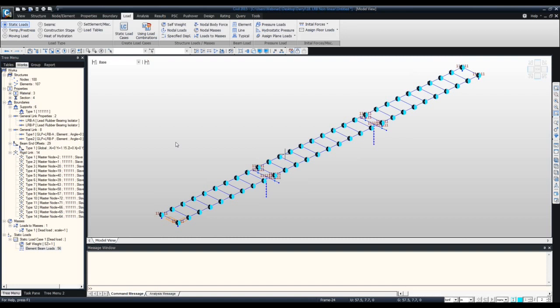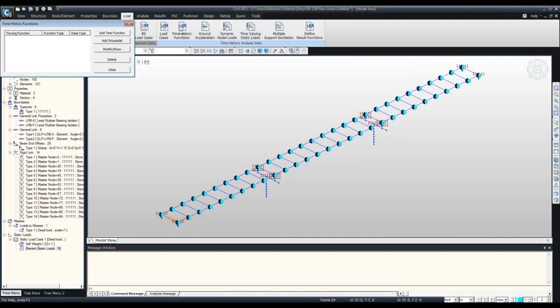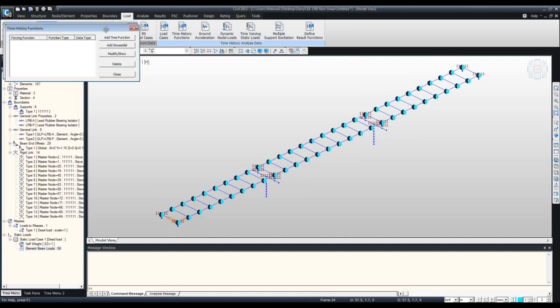So we'll call this a ramp function. Okay, so a ramp function is assigned to the static dead load, and we'll use a couple of time history graphs, or just preset graphs for our project. In order to go to our time history load, make sure you're under the Load tab, then under the Load type, select Seismic, and then select Time History Data. So, Time History Data function.